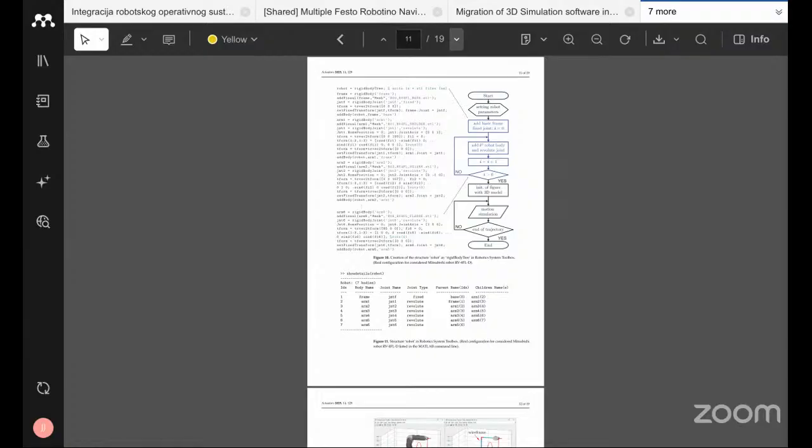So the physical parameters such as arm length, link masses, moments of inertia, center of gravity, joint axis, geometrical envelopes, and collision bodies. Then kinematic verification. We have our DH transformation we discussed in section 4.1. We can verify it using the MATLAB functions.